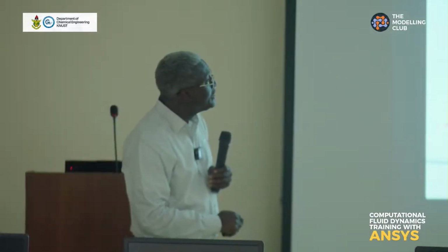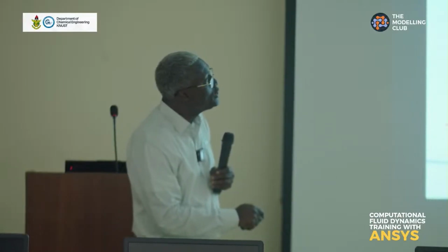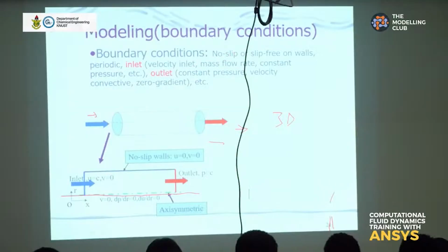And if you were to draw the velocity profile, particularly with the no slip condition, you see that it will be somehow parabolic. I wish I had something to draw it. It will be parabolic, so there will be variation of the velocity radially, but when you come to r equal to 0, it is 0.